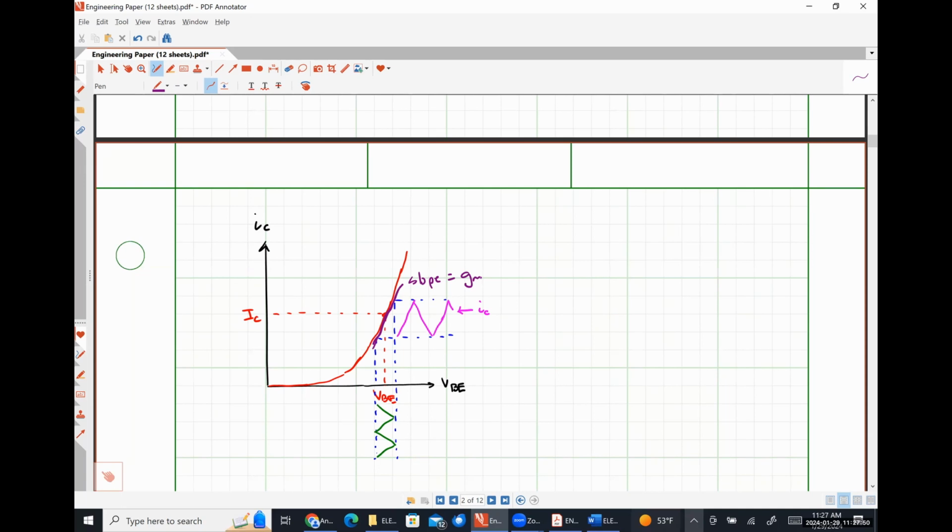We do. We put some input signal there. So we establish some DC operating point, and then we have something that we want to amplify, some small signal that we want to amplify. So that could be the output of some sort of sensor that's only capable of giving us very, very small voltages due to how it responds to some external stimulus. That external stimulus could be literally anything, right? It could be a piezoelectric transducer, which converts mechanical deformation into a small electrical signal. Could be a nickel strain gauge or something like that. Just anything that gives us an output voltage due to some sort of external response or external stimulus.